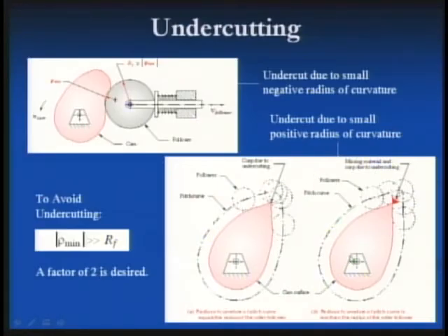So here's a depiction of what we're talking about. Instantaneous radius of curvature of the cam varies as I travel around the cam. While I want to dwell, it will be constant at the radius of the cam, but where the cam shape is changing, the radius of curvature is changing continuously. I want to avoid either of two situations.